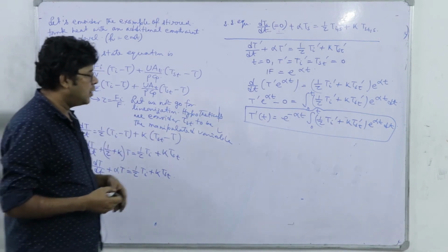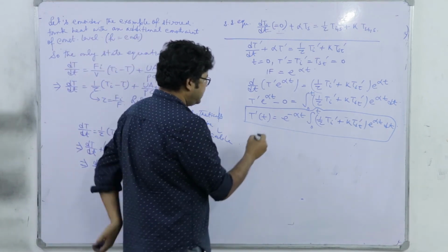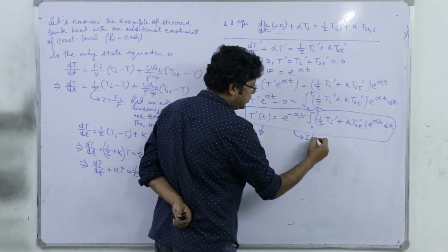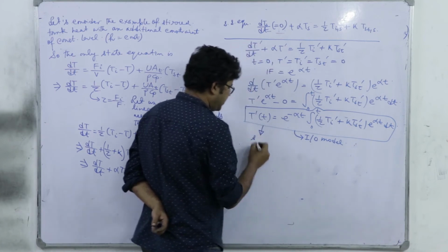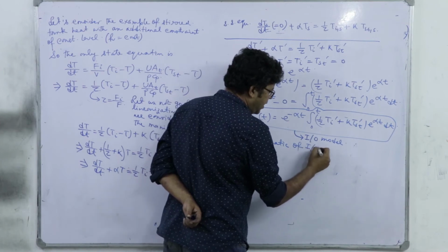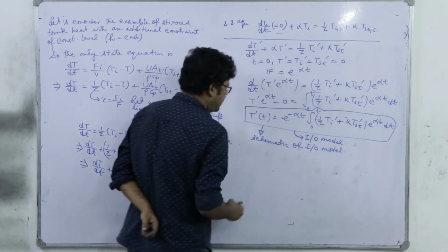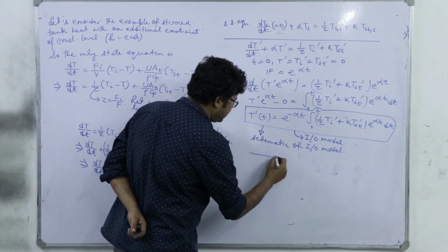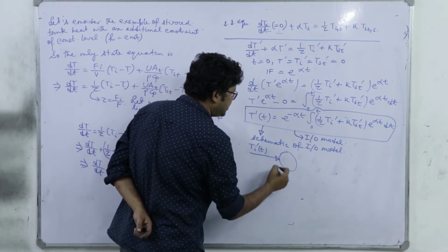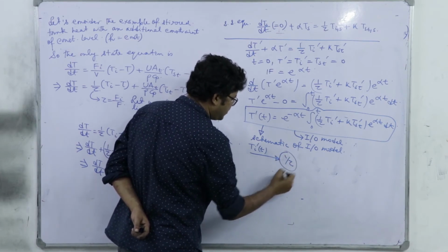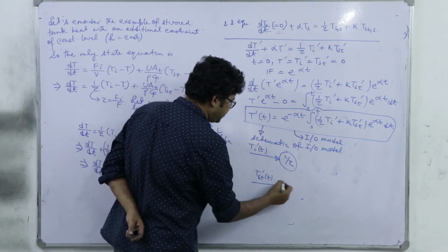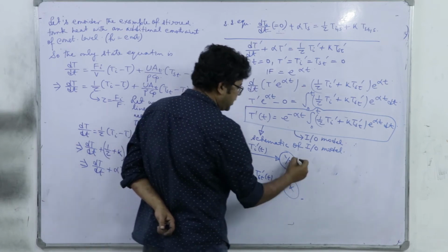That's the typical input output model, and if you go for a schematic of the IO model, Ti'(t) will be the input, there will be a multiplier block 1 by tau, then Tst' another input, another multiplier block k.